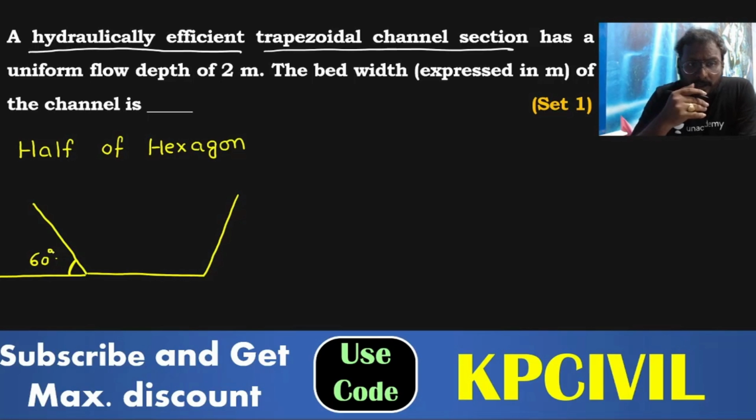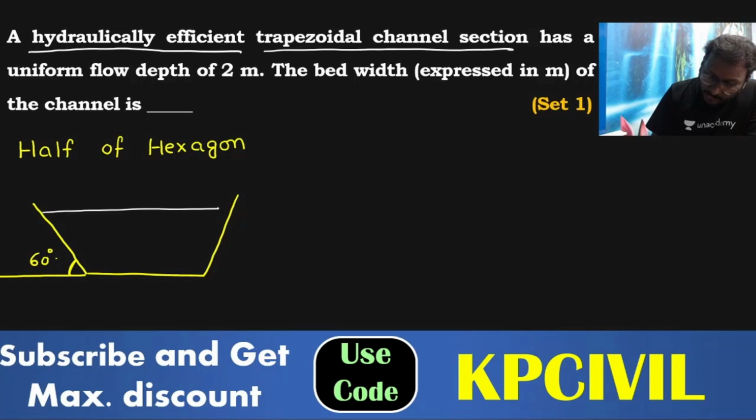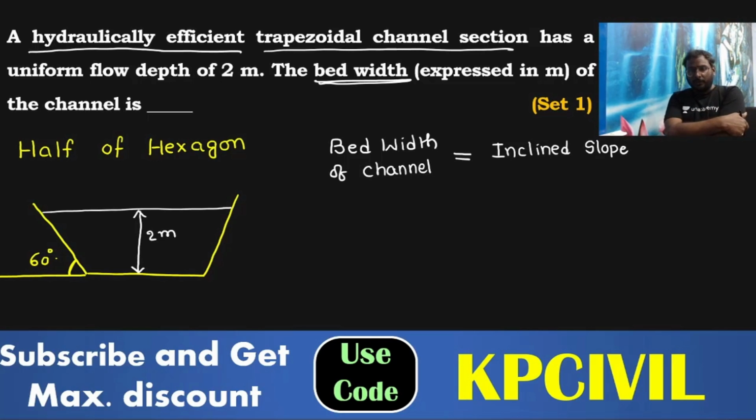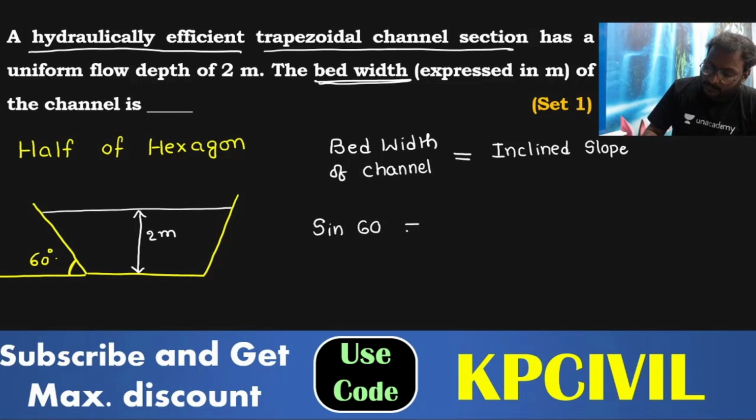Now, this section is carrying a uniform flow depth of 2 meter. Find the bed width of the channel. For a hydraulically efficient trapezoidal channel section, which is exactly half of a regular hexagon, the bed width of the channel is equal to the inclined slope. How do you get the inclined slope? We have the formula, with an angle of 60 degrees: sin 60 is equal to flow depth by inclined slope.